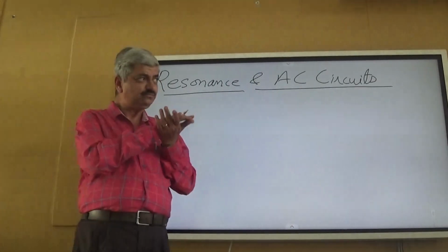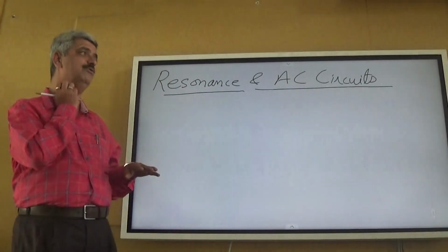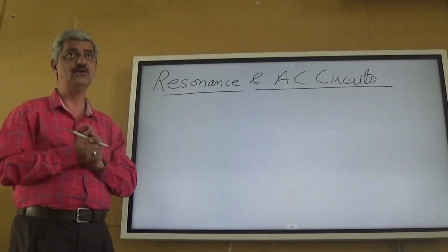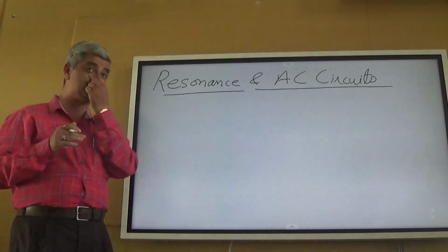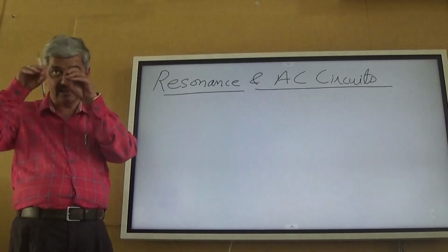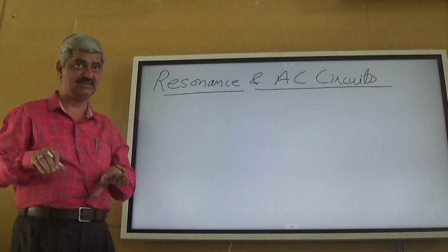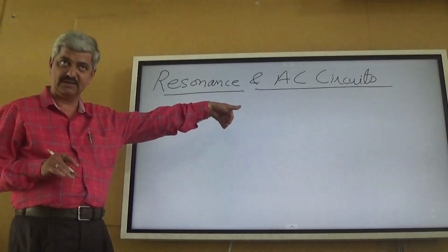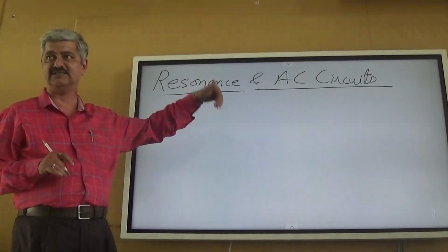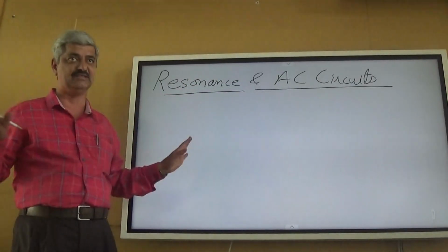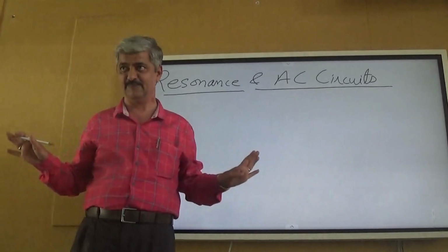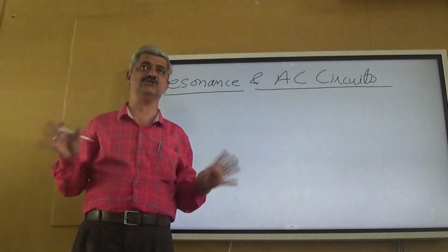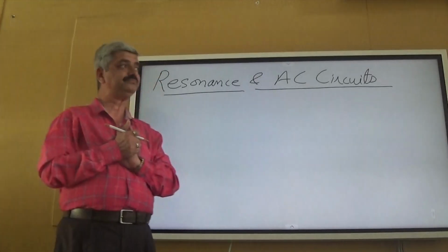Therefore, we have multiple options of finding the answer: either by classical solution of the differential equation, or by assuming that the solution is sinusoidal of the same frequency, or by considering impedance to be j omega L for an inductor and 1 upon j omega C, or minus j upon omega C, for a capacitor. I hope the ideas are quite clear now. Is it okay? So any circuit which consists of an AC source, we can solve using this.